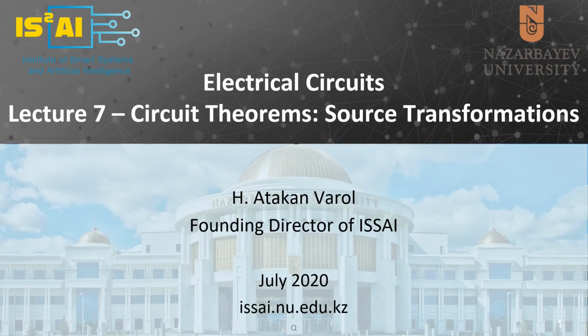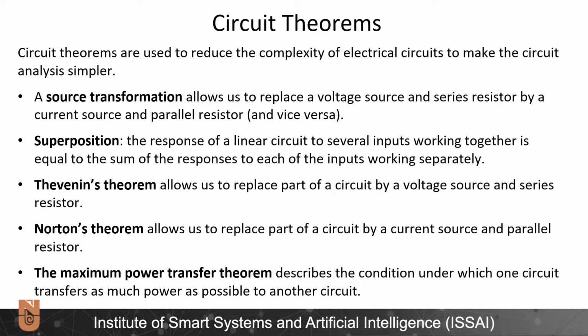In this lecture, we will cover our first circuit theorem, which is the source transformation. Circuit theorems are used to reduce the complexity of an electrical circuit and make the circuit analysis simpler. In the source transformation, we replace a voltage source and series resistor by a current source and parallel resistor, or we do the opposite operation.